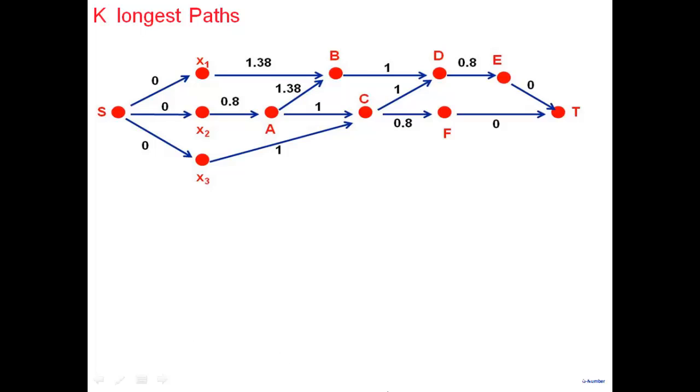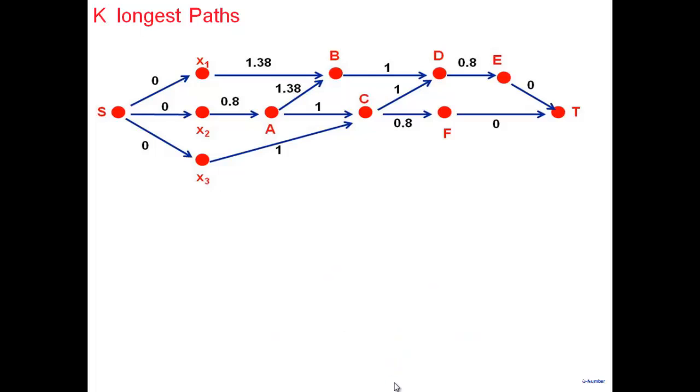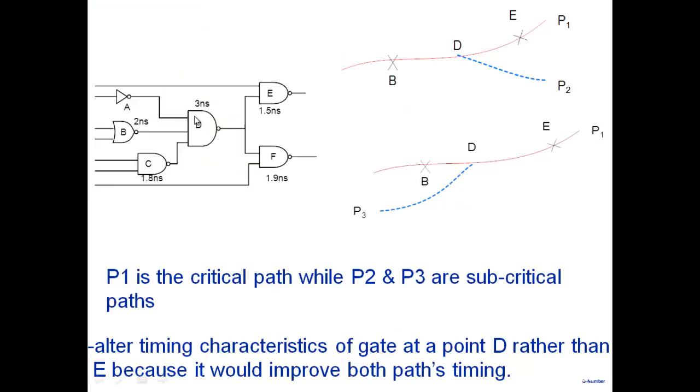So it may happen that we do all of this here and we fix our timing, but our delays are not complete at this stage. When will the complete value of delays become available? After I get a transistor schematic, after I do the full layout, then I will know exactly how long this wire between A and D is. Then from the length of the wire, I'll recompute the delay of my gate A, taking into account the length of the wire. Then I'll have a very good estimate of the delay of that particular inverter A.